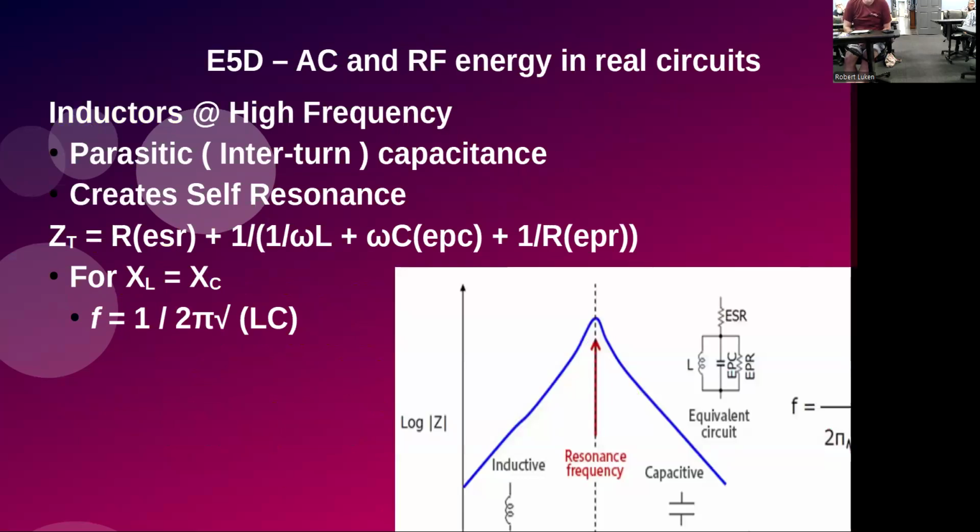If we look at the frequency plot for that inductor, we can see there's a resonant point, because you've got L and C with the parasitic components, the interwinding capacitance and the inductance itself. So it's going to resonate at some frequency. And then you've got some effective series resistance in there, which is going to affect the Q of that. So it will affect how sharp this curve is that they're showing. And there's the formula again for resonance.